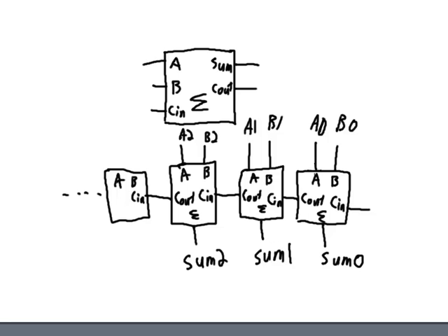So from the beginning, we've got 10 nanoseconds plus another 10 nanoseconds, and so we're up to 20 nanoseconds before sum 1 is valid, and Cout will be valid at the same time as this bit. So we will be applying Cout 20 nanoseconds later, and then it's going to be another 10 nanoseconds delay before sum 2 is valid. So it's going to be a 30 nanosecond delay before sum 2 is valid.